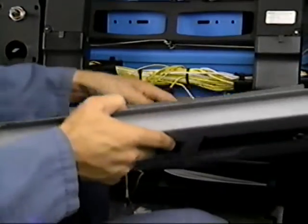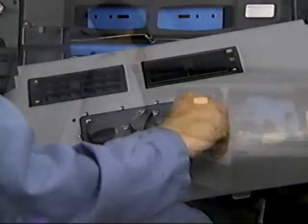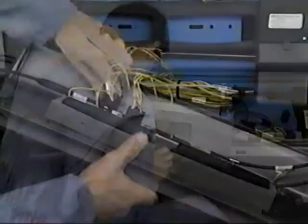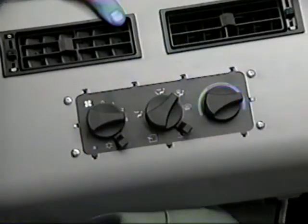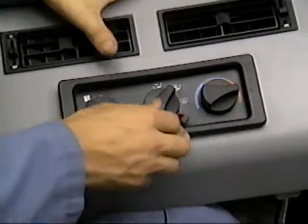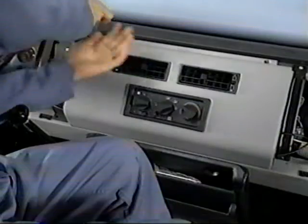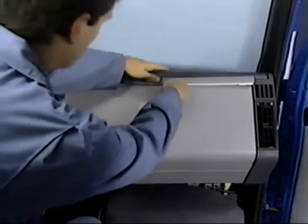To install the new control panel, first mount it to the dash panel. Attach, install, and adjust the cables. Insert the panel light and connect the wiring. Reinstall the bezel around the control panel. Close the center dash panel that contains the control panel. Then reinstall the dash panel to either side of it. Finally, reconnect the vehicle's batteries.